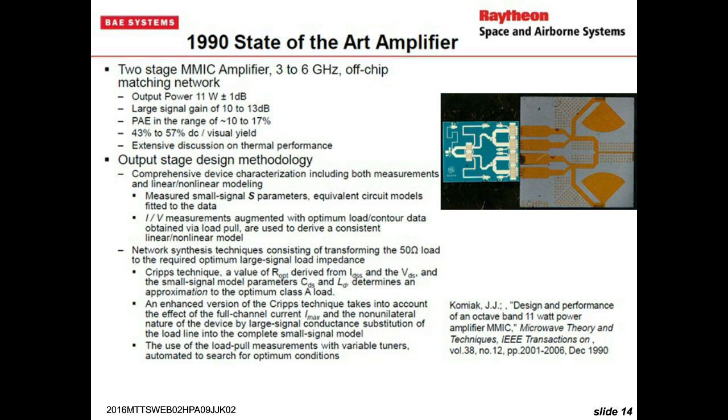I think it really is not the transistor technology that you use, but really can the resonator, whatever frequency determining element that you're using, take the power to be able to provide the proper feedback to get oscillation. So I think that would be the determining factor. But I'd also be concerned about the effect of thermal characteristics on the noise of the transistor if you push the power output too far.